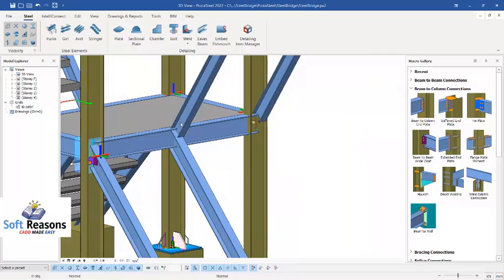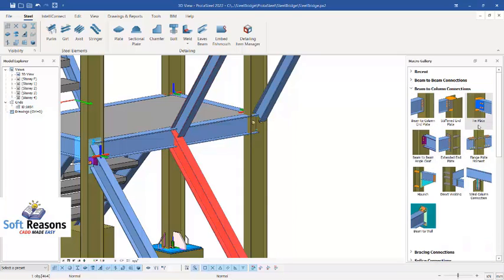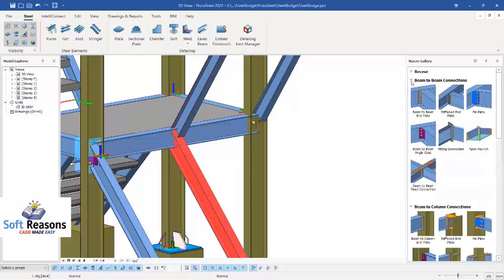For this one, see this connection right here. Fin plate can work here successfully. Also in these provisions, fin plate will be perfect. If you want to proceed, you can also check this. This is fin plate beam to beam, and then we also have fin plate column to beam. So we can use any of these two in these provisions and they will work fine.